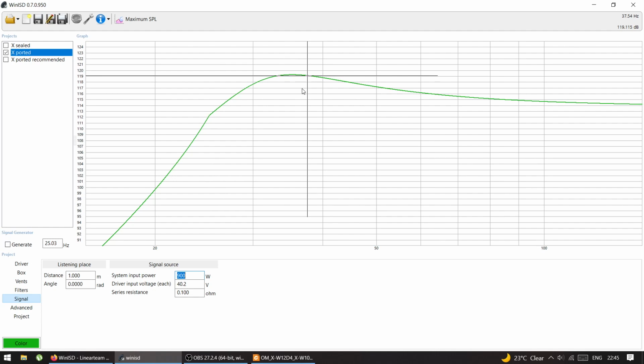And I'm perfectly happy with it because the songs that I have, I made a playlist of songs below 30 hertz. Most of them are like 28, 27 hertz, and all the other hip-hop songs are like 30 hertz. Yeah, 30 and 35 hertz. So this design is for my kind of taste of music and what I like. If you want to design a box for, let's say, electronic music or drum and bass and that kind of stuff, contrary to popular belief, that music is not that low. It hits in the 40 hertz range, somewhere around here. Yeah, it's not low.